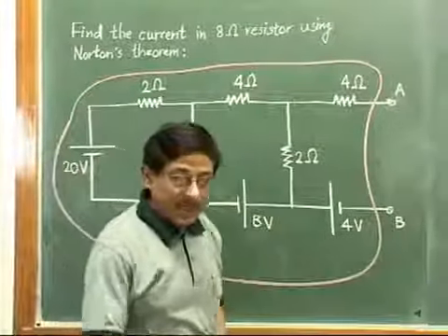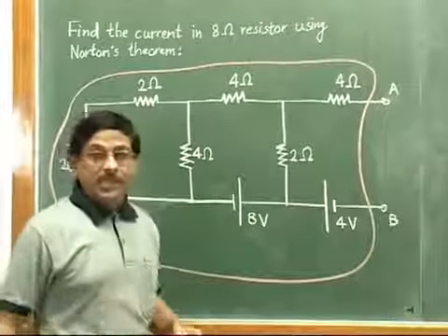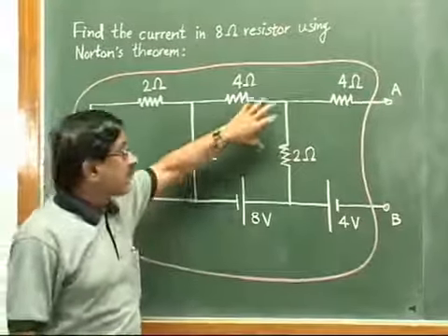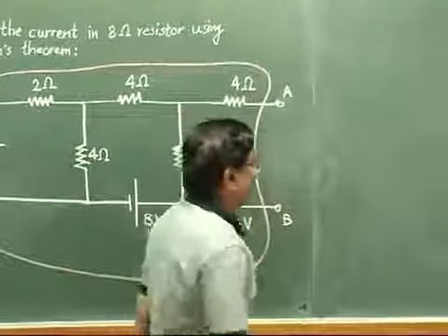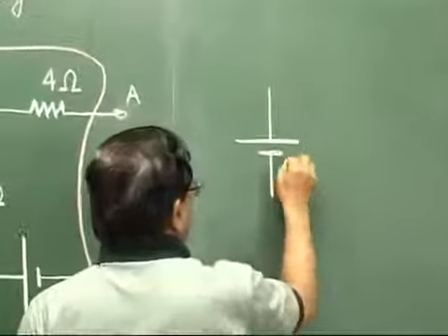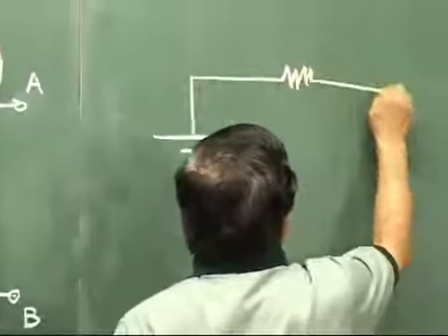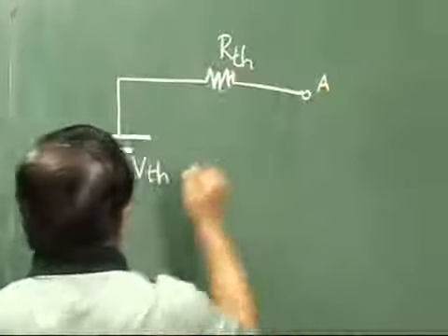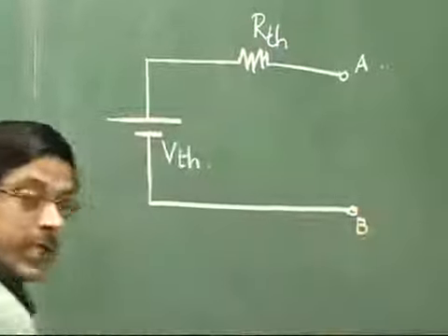Again see what is the central idea now. Central idea of the Norton's theorem. Okay. In Thevenin's theorem, what we did was we converted this particular circuit into the red space with the help of, or say in terms of, some equivalent voltage source VTH like this, called as a Thevenin's voltage, and then one single equivalent resistance RTH. Okay, and so this was our point A and this was our point B. So this was done in the solution with the Thevenin's theorem.